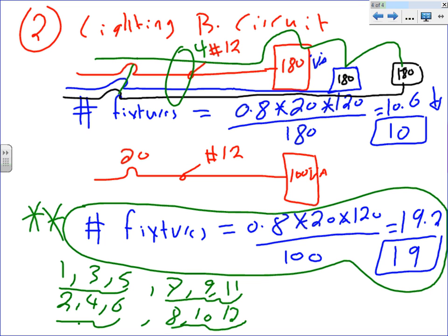If you have a tiny little motor, a 5 horsepower motor, where you need to pull number 10 conductors, you might be able to pull them through the same conduit system. Yeah, you can. I would group number 10, number 8 conductors for motors. Number 6, 8, 10, not a big deal. Higher than that, you need a dedicated circuit. But you're going to go by the engineer. If the engineer said dedicated circuit, you're going to give a dedicated circuit with conduit.